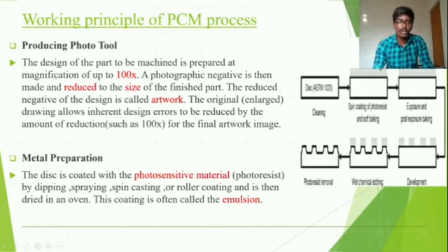The reduced negative of the design is called artwork, and the artwork is then transferred onto two mylar films, which are used to transpose part images on the metal.